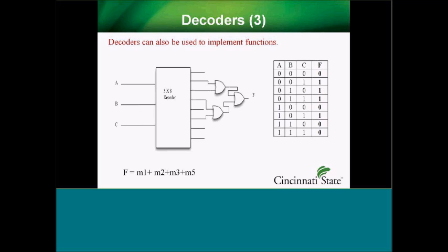So a lot of times in my problems that I'll give the students, and I'll show you some of these after we go through these PowerPoint slides, I'll give them a problem. I'll say, okay, here's a problem. You build the truth table. I want you to do the K-maps, so write out the function, do the circuit normal. Then I want you to do it with a multiplexer, maybe whatever type of multiplexer, an 8 by 1 or 4 by 1 or something like that. Then I want you to do it with a decoder. And then maybe I want you to implement the entire function with NAND gates or something like this. So I try to show them there's many, many different ways that you can build these devices, with these functions, with lots of different types of devices. And this is, of course, just one approach.